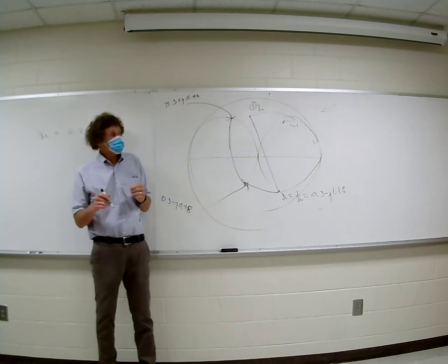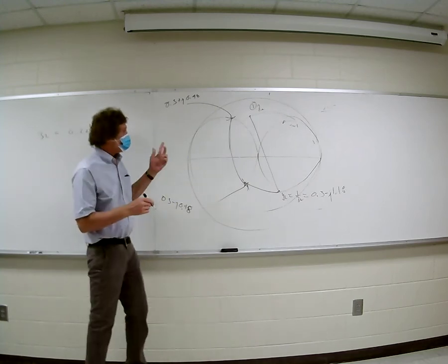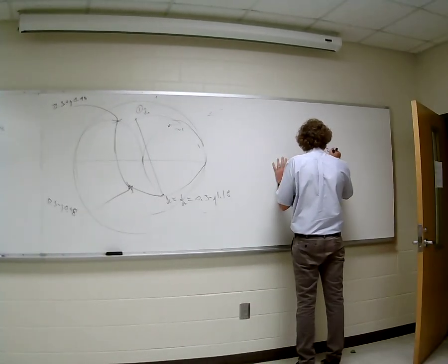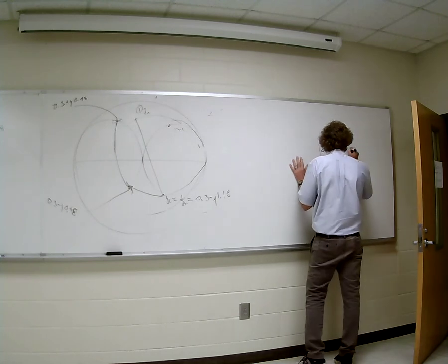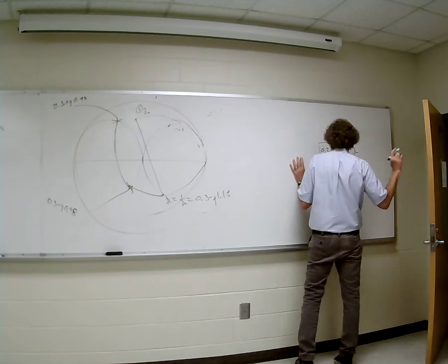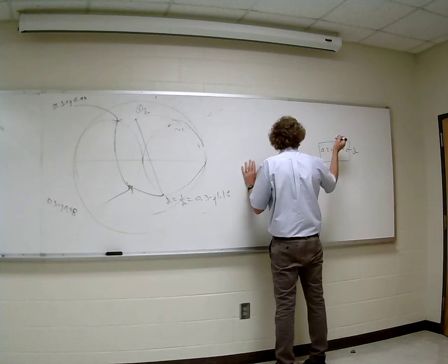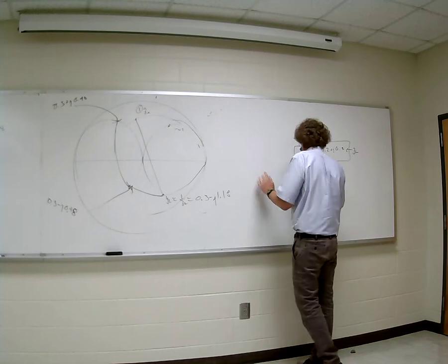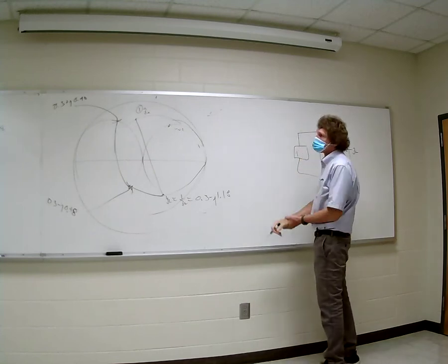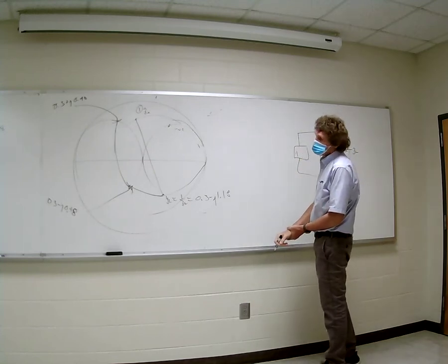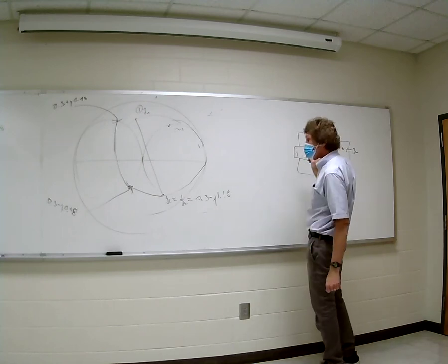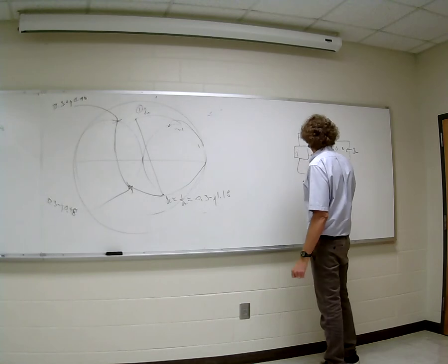So, what's the total value yet? I'll draw this thing. So here's my normalized ZL, 0.2 plus j0.8. That's an impedance. So this is ZL here. Now, I come over, and I'm going to put a parallel element. It's an admittance, and the admittance is what? j what? 1.66. Yeah, that looks right. Is that right? Yeah, yeah.